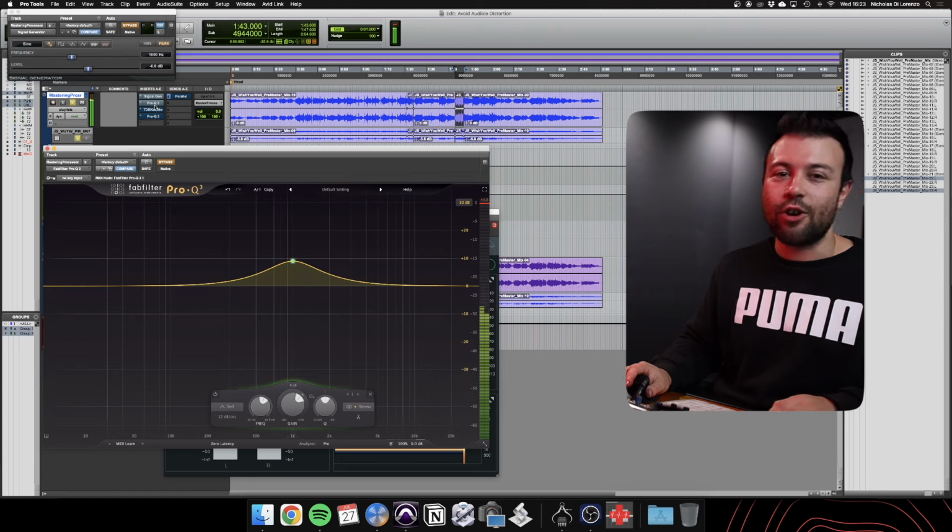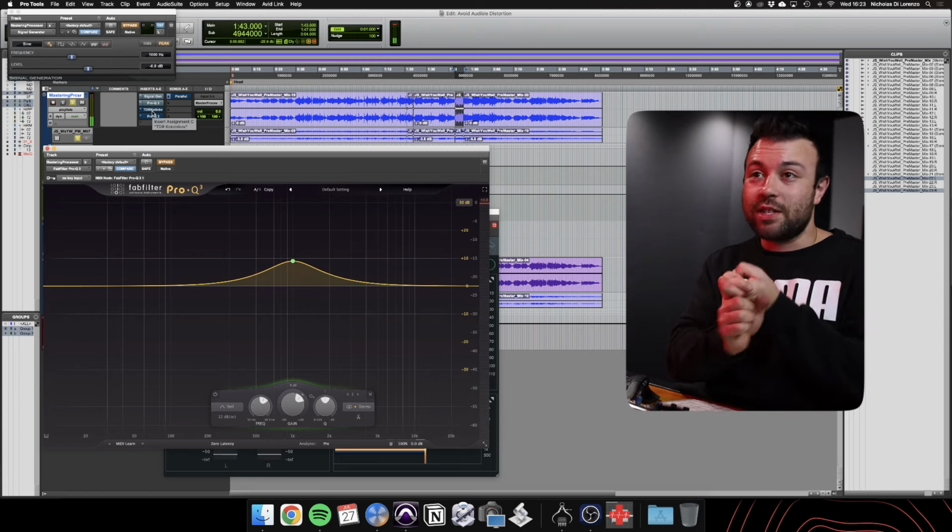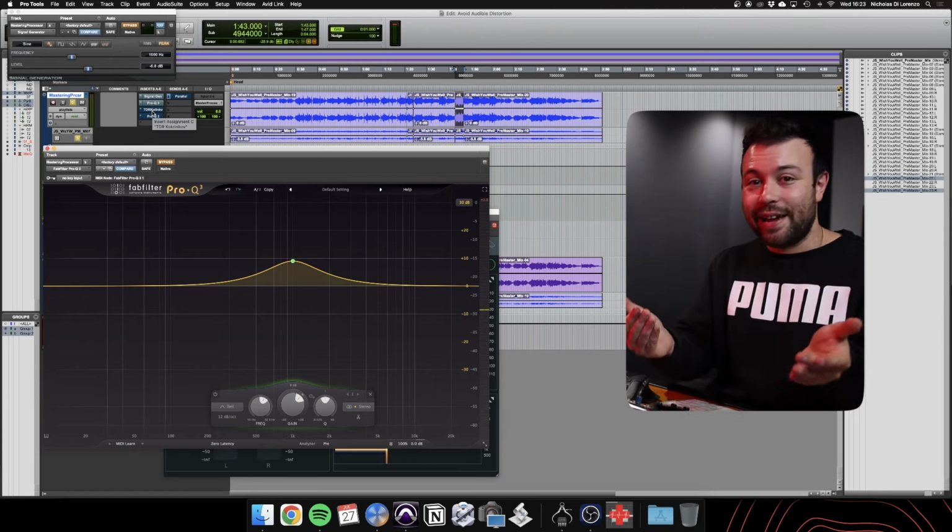I'm going to turn that off. That is horrible noise. And so that's the first reason why gain staging is so important. You want that headroom. The second reason is because many analog emulations, like I use Vertigo VSC2 sometimes and the SSL channel strip, they react in a non-linear fashion to the source material based on the level of the input.